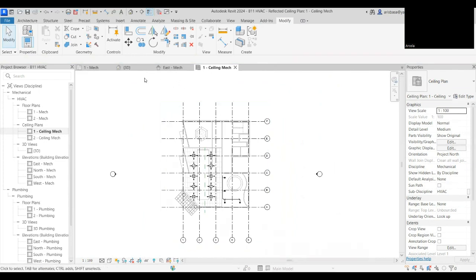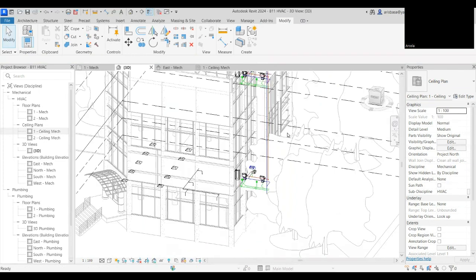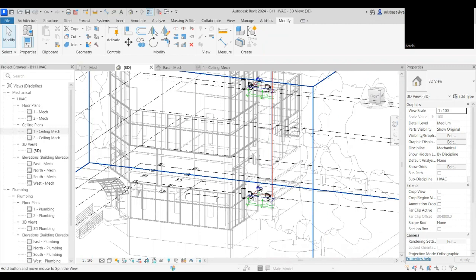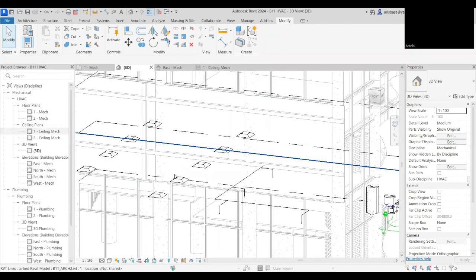Okay, so let's look at the 3D. So you have now those guys. So you can imagine now next week you will see some big ducts connecting to that, right? But the concept of that is similar to the piping as well. You make the big main duct, and then you connect these guys, and then you have to have a proper height. That's why it is critical to know the ceiling height and the bottom of the slab, because maybe you don't have enough space there.